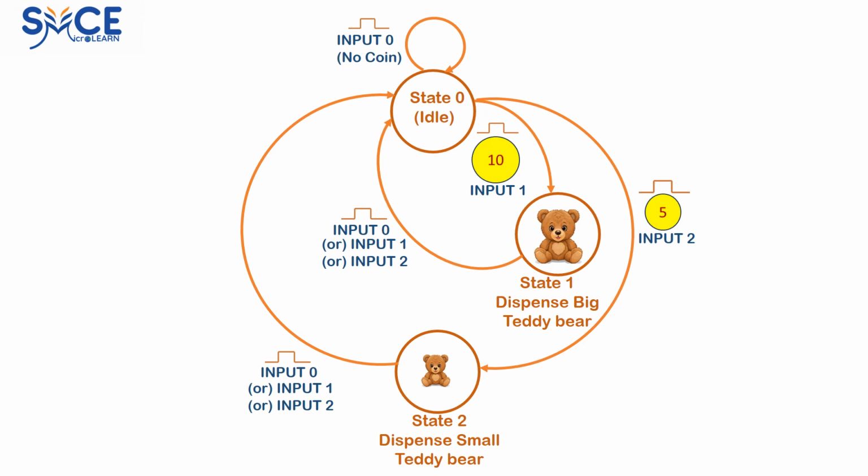Now this state diagram shown on the screen covers the complete operation of the state machine that is going to act as a controller for the toy vending machine. We will now make the state diagram visually simple and clear so that we can embark on the design. As a first step, let's remove all clock pulses shown, as they are anyway needed by default to effect the transitions and need not be shown explicitly.